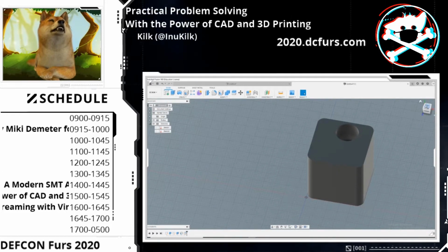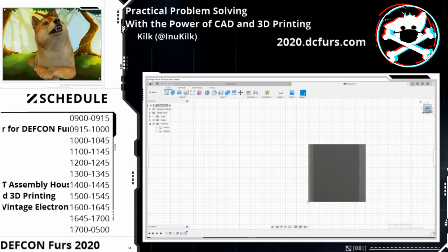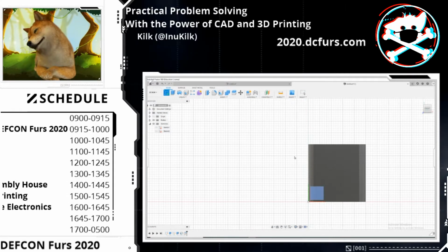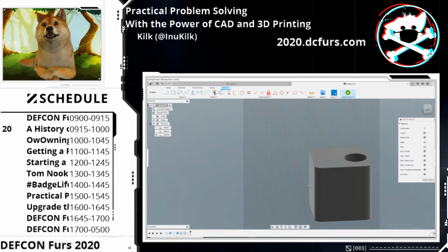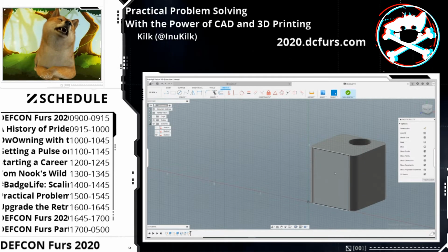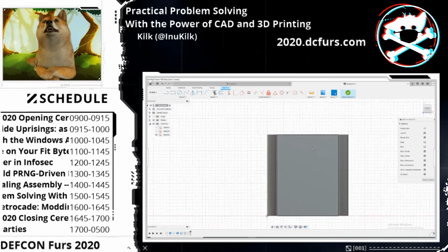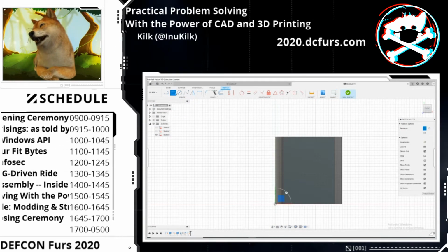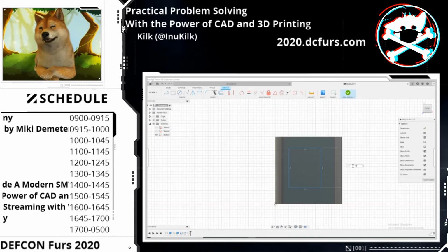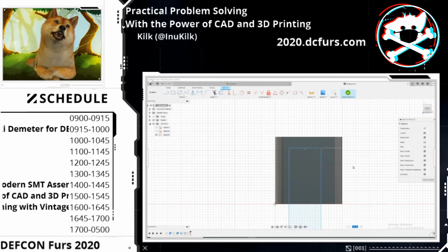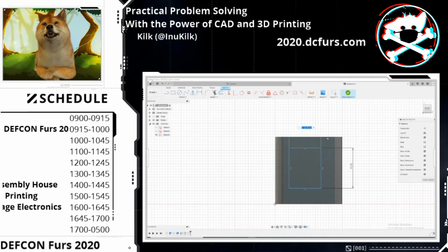Another thing, we're going to do another sketch actually. So let's hit the front view now this time, and let's hit create sketch, and let's select this face right here. So now it's going to create this infinite grid based off of the location in space where this plane is. So we can hit front, and let's do a rectangle this time, and we're just gonna dimension it like that. We'll make this 15 millimeters. Oh, not 125. See, this is why you want to double click and just hit 15. There you go. And dimension here, 10.